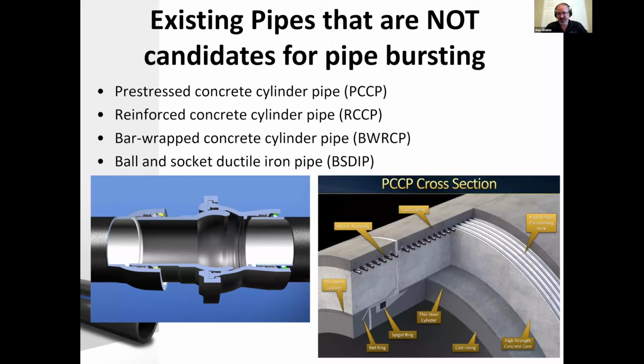So we had a question here about bursting ductile iron pipes to install HDPE. What are the concerns about scarring it? There's a very big difference in the failure mechanism of cast iron versus ductile iron. The failure mechanism of cast iron, when it gets to that top limit of its strength, is that it'll snap, brittle and break apart, and then mix into the soil surrounding that replacement pipe. Ductile iron actually on its curve here will want to elongate as it finally reaches the end of its strength and then wants to reconform back to the existing shape that it had previously.